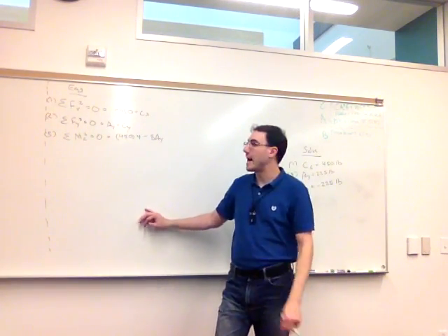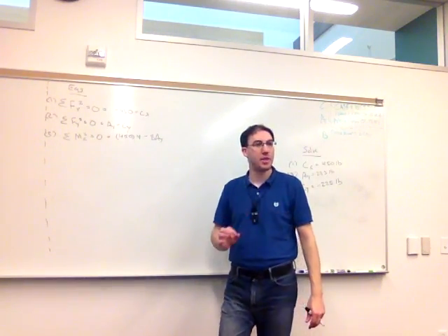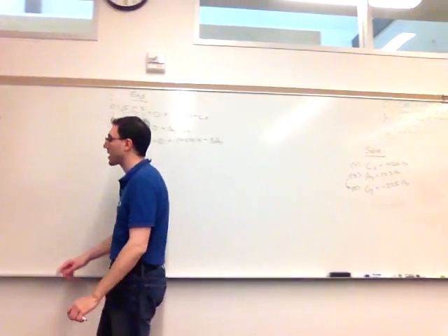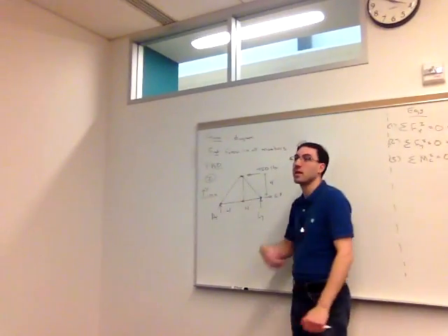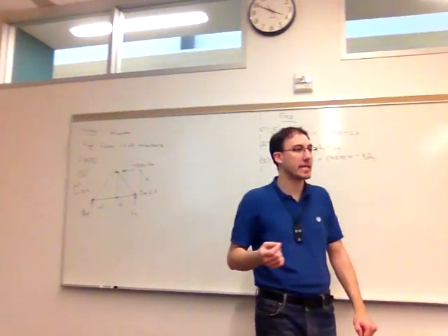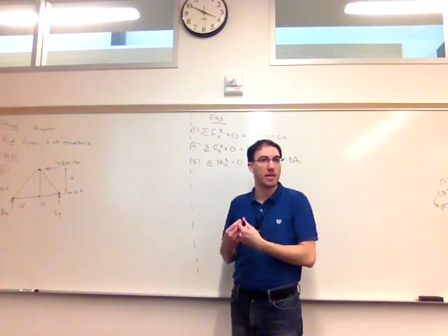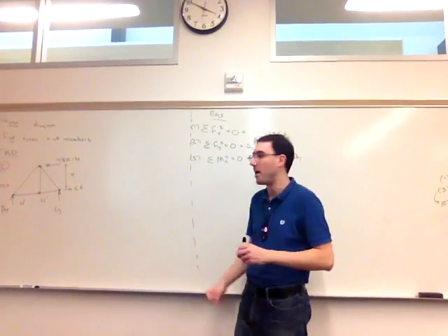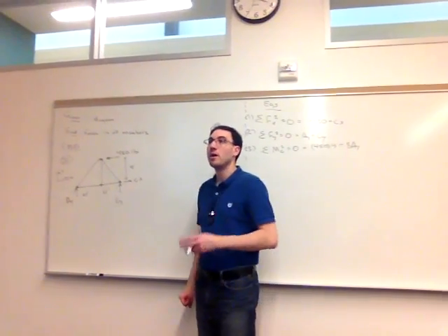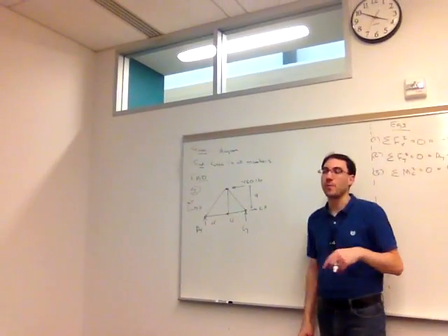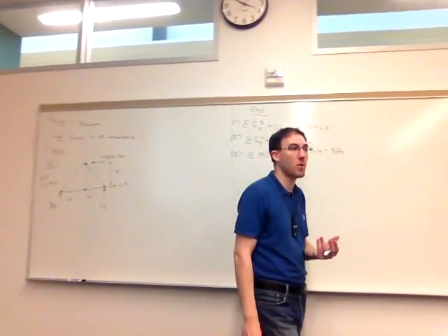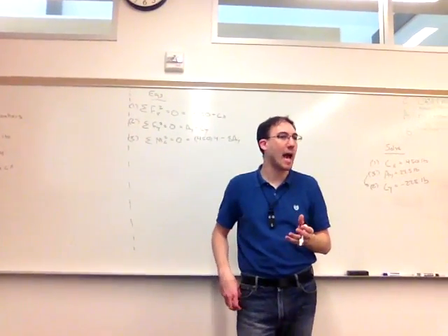So what's new is now to find the forces in the members using method of joints. Now what I do is I look at what is happening to the pins, the pins in this problem being A, B, C, and D, and modeling what's happening to each pin, now we'll be able to see the effect that the members have on the individual pins. So since we're doing this by hand, it's preferable to start with pins that have the fewest things happening to them.